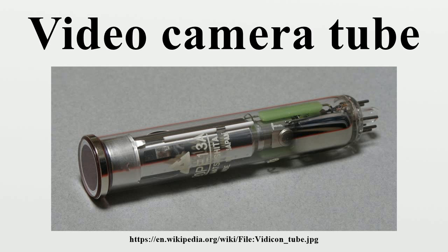It has an efficient photocathode that transforms the seen light into an electron image. The latter is then accelerated towards a target specially prepared for the emission of secondary electrons. Each individual electron from the electron image produces several secondary electrons after reaching the target, so that an amplification effect is produced.